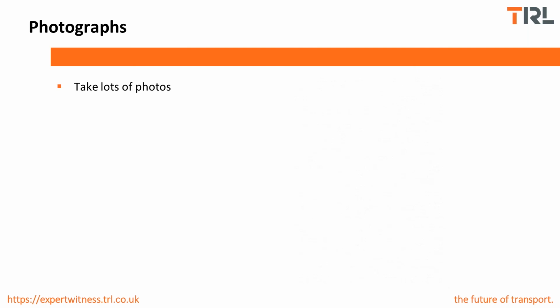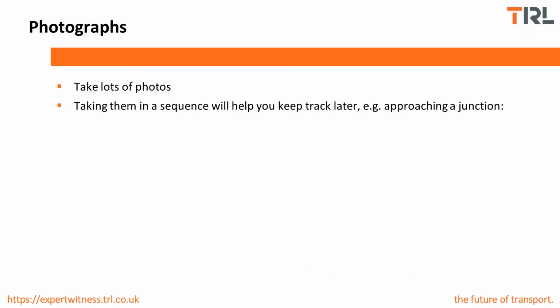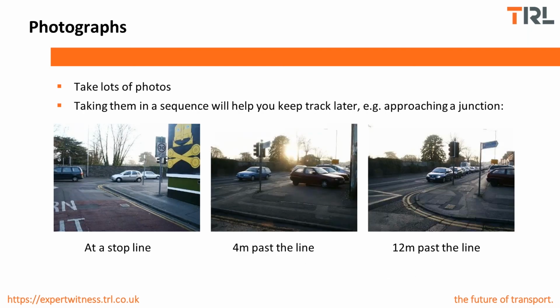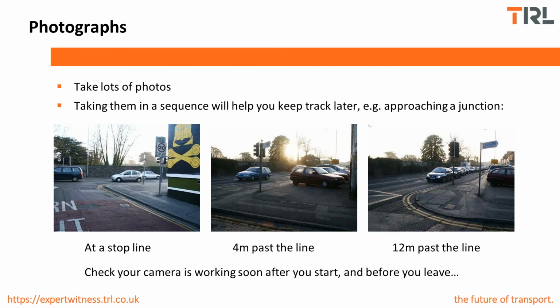Photographs are usually invaluable, and I suggest you take lots of them. It's better than not taking enough. If you take photographs in sequences as you walk around scenes, then it helps you to work out what they are later, for example, on the approach to this junction, but don't get so engrossed in what you're doing that you get run over. Taking notes of what you've photographed may help too when it comes to putting it all together into a report at a later date. And before you leave a scene, I would suggest you do check you've actually got the photos that you expected to, which might save you a trip back there again later.